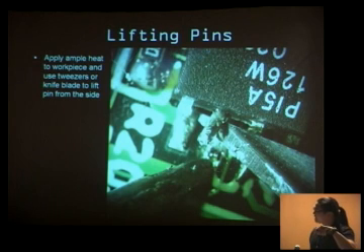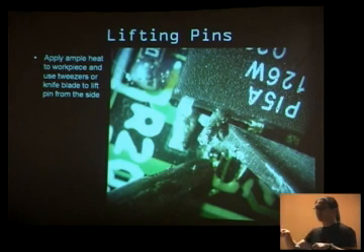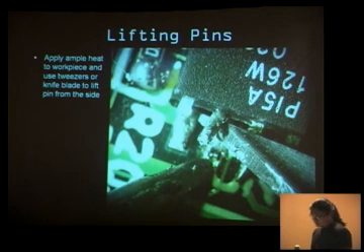What you do is you take your soldering iron, you put it right at the edge of the pin here, and you wait for it to get hot. And you actually wait for the heat to propagate to the whole thing. You don't want to start lifting the pin too early because this guy's metal, and he's going to pull the heat out. If you put it down too early, you put the metal thing in, it sinks all the heat out, and all of a sudden it's solid again. So you wait till it's really hot, you take a knife blade in, and just pry up with it, rotate it back, up comes the pin, and you can go ahead and patch onto that.